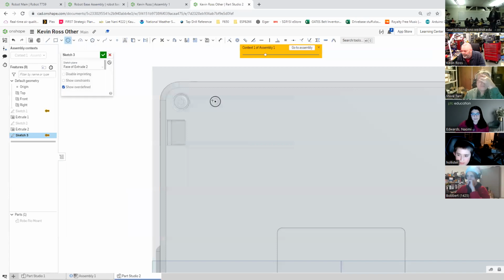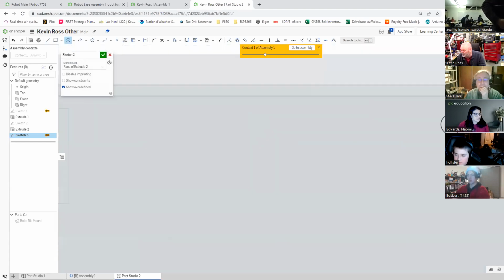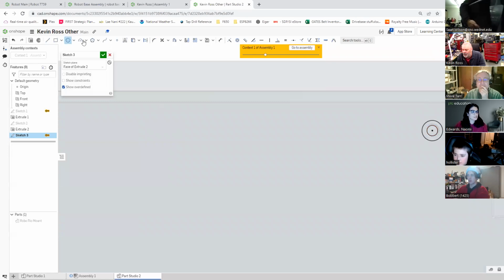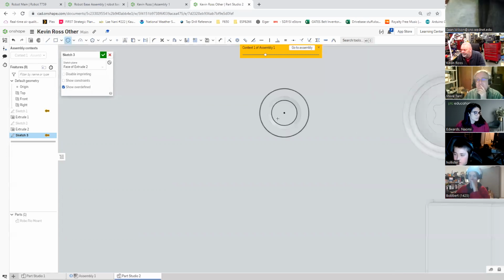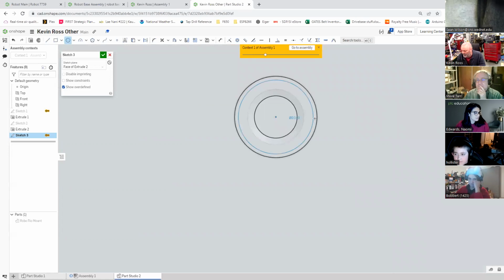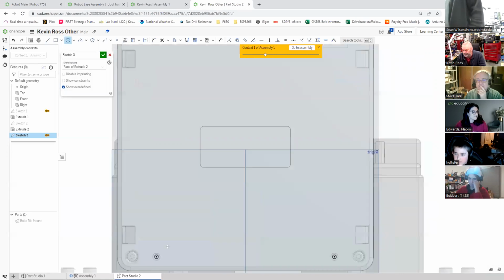and I'm going to go up here. And I believe these to be, I think we need 0.125 holes. They're 3mm screws. And so we'll just do that real quick. I'm going to draw another circle here. There it is. Making this up as I go, but 0.125. All right, so now I've got, you get the idea. I can project all those holes.